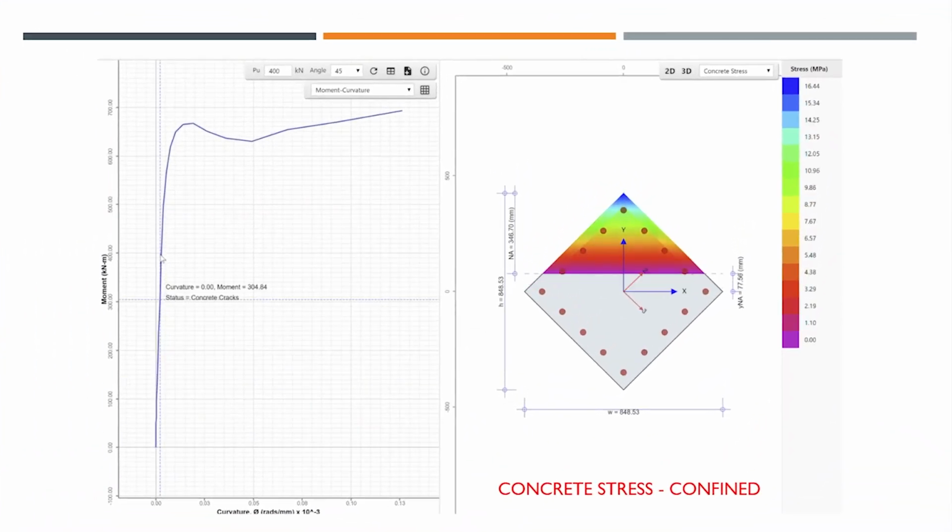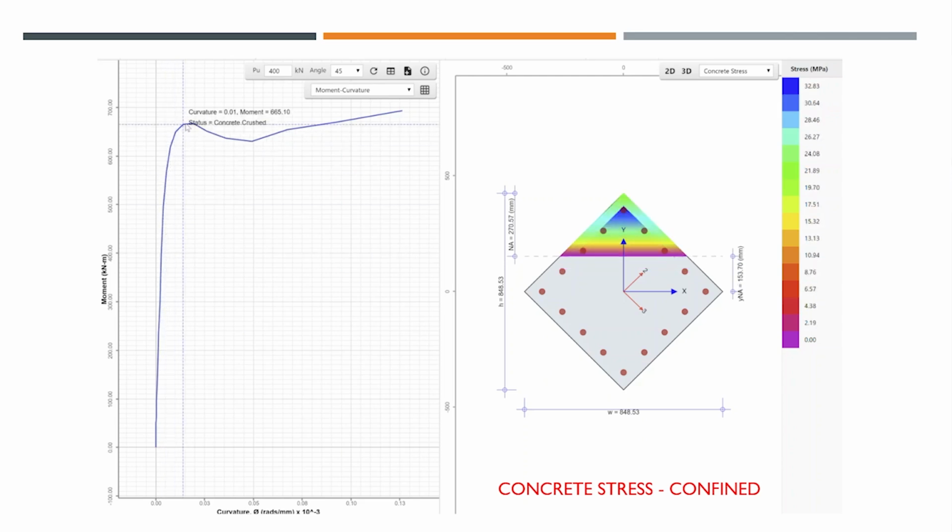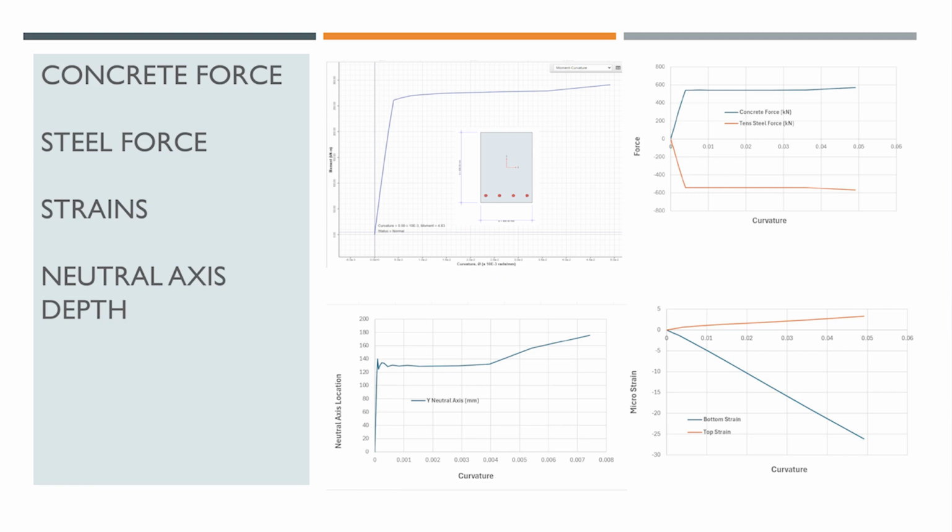We can also see it from another view, and this is an interesting plot, because when you bend the cross section at an angle, not on one of the primary axes, the capacity will reduce a lot, because concrete will crush very quickly in this case. And as you can see from here, as it goes up, the portion of concrete in compression reduces significantly, so the moment capacity will be much less, and also the curvature capacity, as it drops from here. That portion in cover is gone, more cover is gone, and then only a small portion is left in the middle to carry, and finally that will also be gone. So that's the plot.